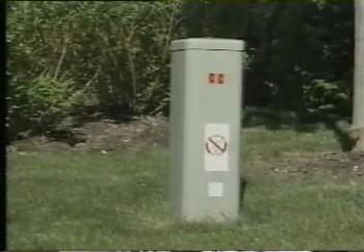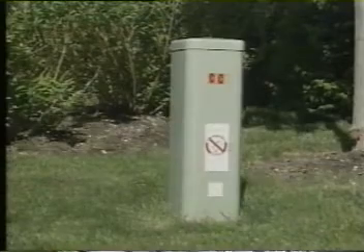Now, in some of the newer areas, telephone poles are not considered to be particularly aesthetic. So to make the areas look more wide open and more aesthetically pleasing, the telephone company buries the telephone equipment or puts it underground. So if we go back to this customer's house, they would have a little interface box on the side, but at this point it would go down and be buried under the ground and would probably go to a backyard or other access point where you might find a small metal box sticking up out of the ground, referred to as a pedestal. Opening up that box, we would see the connection points for that customer's drop to be attached to other customers' equipment and part of this larger cabling.